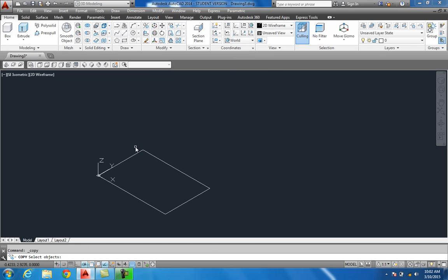And when I'm doing something in 3D wireframe, I just go ahead and draw the whole object out in a box. So click on this, click the center point, and I'm at 0, 0, but I want to hit add anyways, just if you're not at 0, 0, it's just a good habit to have. And what I do is I want to copy it 0, 0. X and Y I want it at 0, 0, but I want it to go up in Z 2.5.